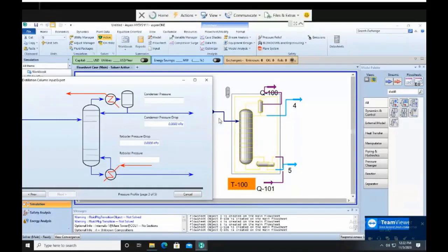So this one has to be with the highest pressure, then this is the second highest, and this is going to be the lowest pressure. Then for that, we have to estimate it. So for this case, let's estimate it. The pressure going in is 7.2. We can say I want to make the change of pressure between 4 and 5 about 1 bar. Okay, so this is 6.2, 7.2. Let's estimate this one to be, I don't know, 6.8, 680 kilopascal. Okay, and this one 580.